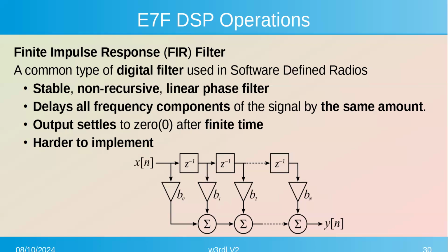So you're basically taking, when it comes in there, you're taking the input, going into that Z minus 1. X[n] is your input. Right, and then it's taking the output of that, then Z minus 1. Well, yeah, those triangles are coefficients, and they're multiplied times the sample, and you sum them all together.